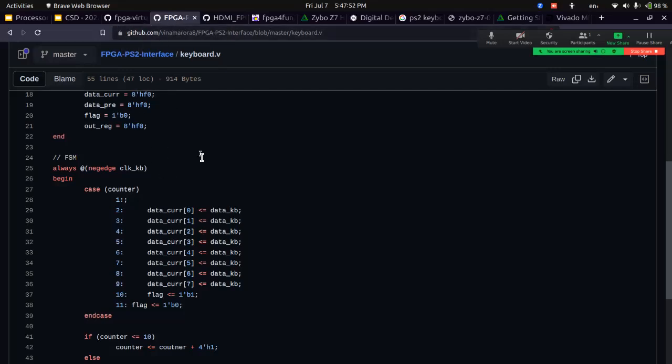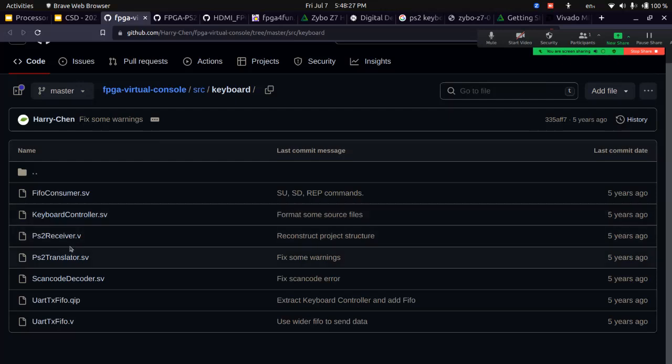And for the keyboard, what you can try is that whenever I press a key, let the LEDs display that. Like when I press A, the scan code of the letter A is hexadecimal 23. Then let us just display 23, the last 4 bits being 3. If you are able to display that particular scan code on the LEDs, that's what we tried first. We can also try that. Then you can say that you have hold of the input, you are detecting the input. Now, once you detect the input, where to store it, I'll be telling you now.